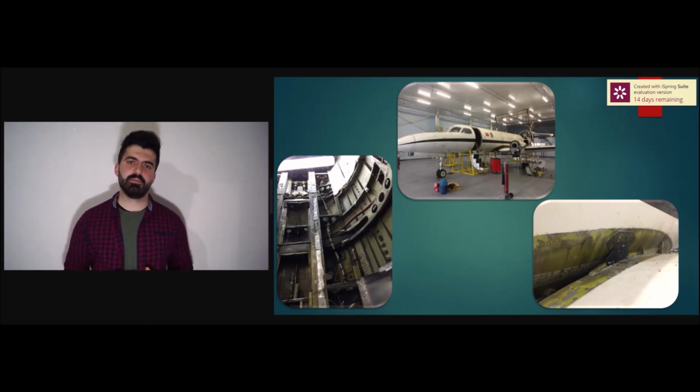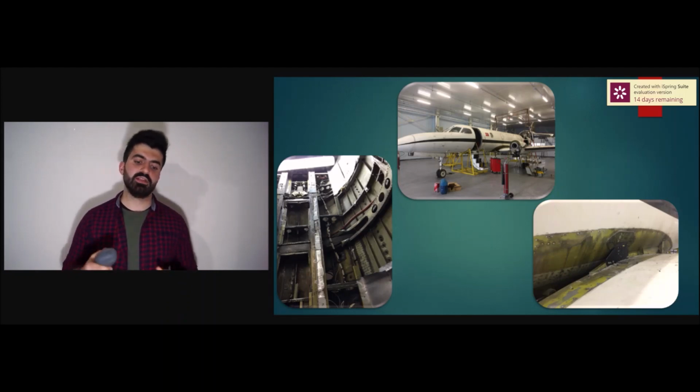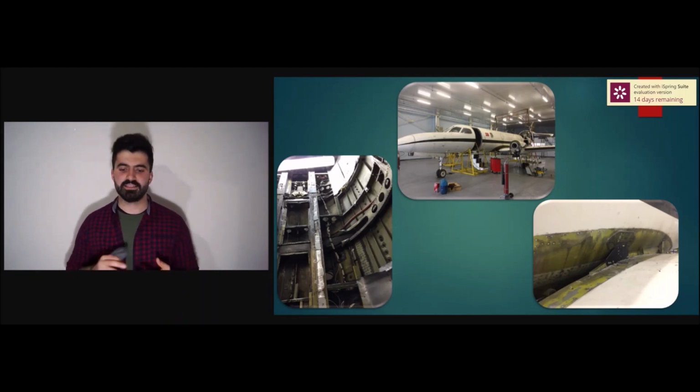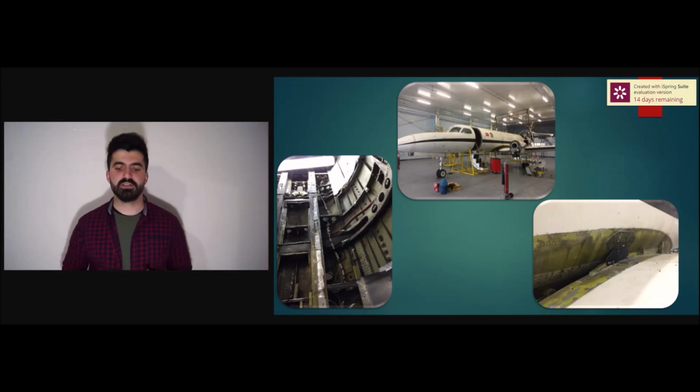As we said before, several factors influence the selection of a structural material for an aircraft. But amongst these, strength allied to lightness is probably the most important. And the properties that we discussed before are stiffness, toughness, resistance to corrosion and fatigue, ductility, and the cost.